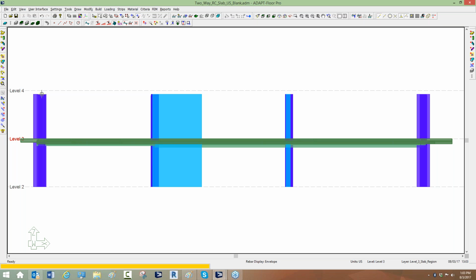So today we'll be working in what we call single level mode as compared to global mode, which allows us to model a full multi-story frame in the software. We'll be working mainly in single level mode, and the way we tell which mode we're working in terms of analysis is from the Story Manager toolbar. There's an option here to toggle between single level mode and also full structure. We also call this global mode or multi-story mode, multi-level mode. Those all essentially mean the same thing.